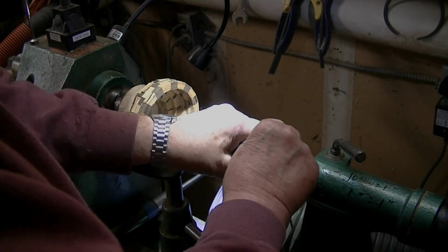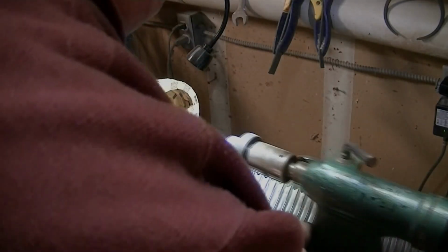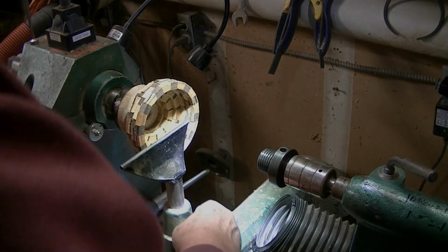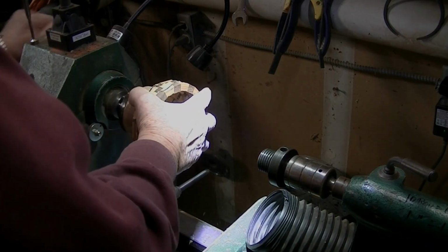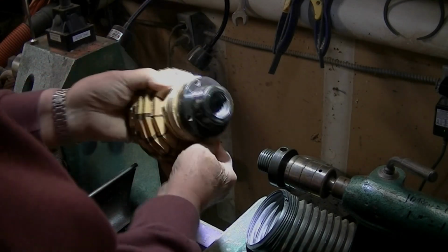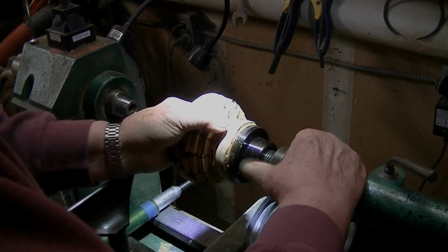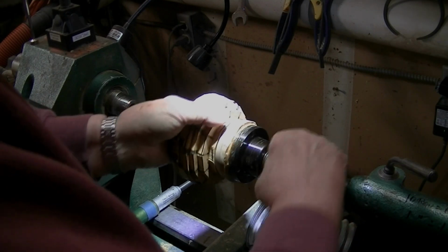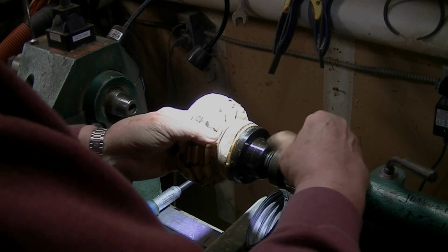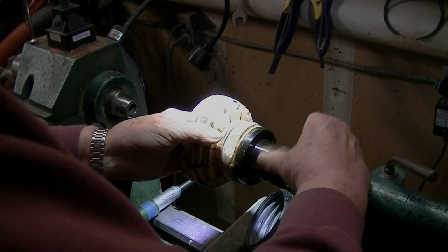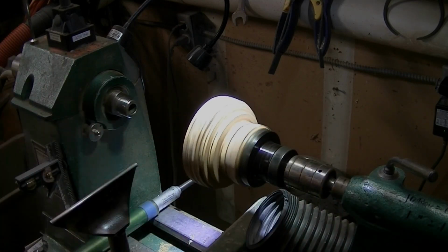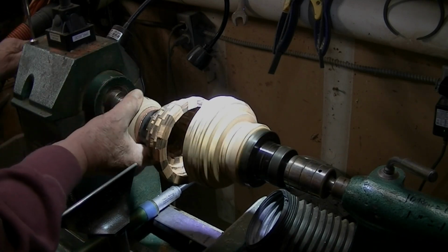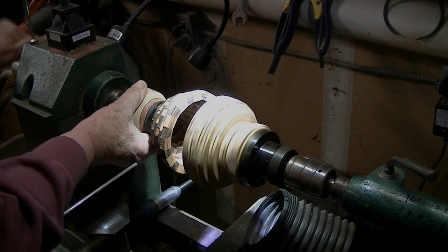So now we're going to put the two pieces together and complete the outside shape. I've added a device to my One Way live center system that will allow me to screw the top section of this vessel onto the tailstock with perfect alignment. Once we get the thread started on it, there are several different thread sizes that are fastened to the One Way live centers that will give you capability for whatever your lathe may be. So that's the top half. Here's the bottom half going onto the headstock.